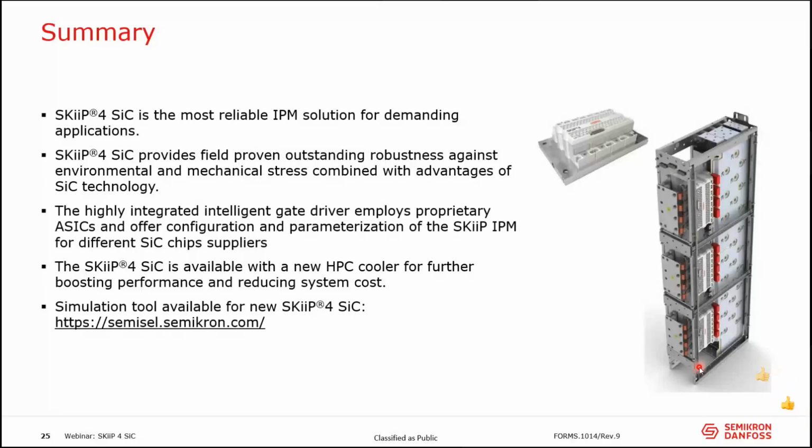All right. A few people asked about this. What is the maximum switching speed of the SKiiPs? So with the driver and everything. So the driver is not the limiting factor. In general, we also have a possibility to 20 kilohertz up to 30 kilohertz, but in general, the application needs to be checked. So if you have some concrete application case, let us know. We can make some simulation. We can make the calculation of what will be possible to understand the safe operating area and the possibilities for the SKiiP, but driver is not a limiting factor. Not the limit, more on the application.